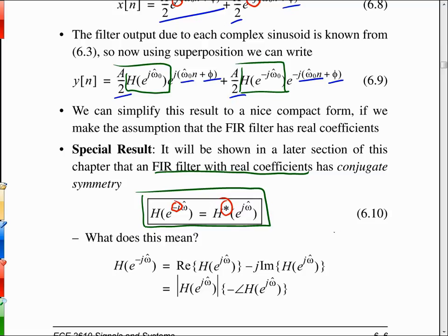And the symmetry idea is if we think of the frequency axis here, that's omega hat, so let's do it like this. That's omega hat, and over here we have minus omega hat and 0. So what we're saying is if we consider the frequency response at this point versus this point over here with respect to varying frequency omega, we have the conjugate at the minus omega frequency relative to the result at the plus omega frequency. So that's the conjugate symmetry.